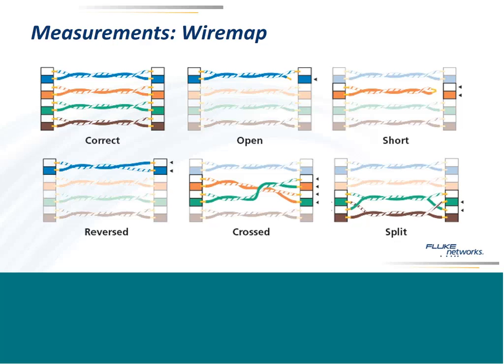That's not okay, because what will happen is the transmit and receive pairs will be twisted together, say, for example, the positive transmit and receive pairs instead of the positive and negative. What happens is instead of the signals canceling out, as we showed in the earlier example, they'll actually be constantly together all along the length of the cable. The crosstalk will be tremendous, much more than if they were just straight, and the cable won't work. And once again, as I pointed out, sometimes these kinds of things will work for a while, or sometimes they'll have a lot of errors.